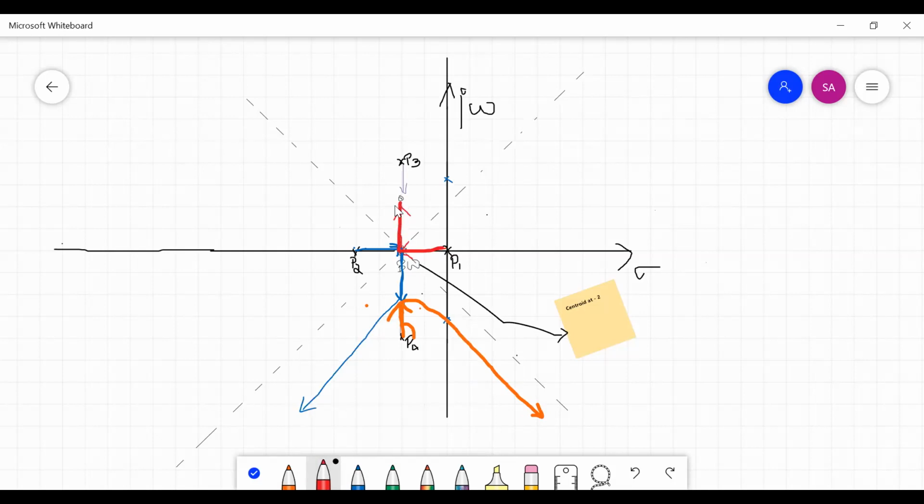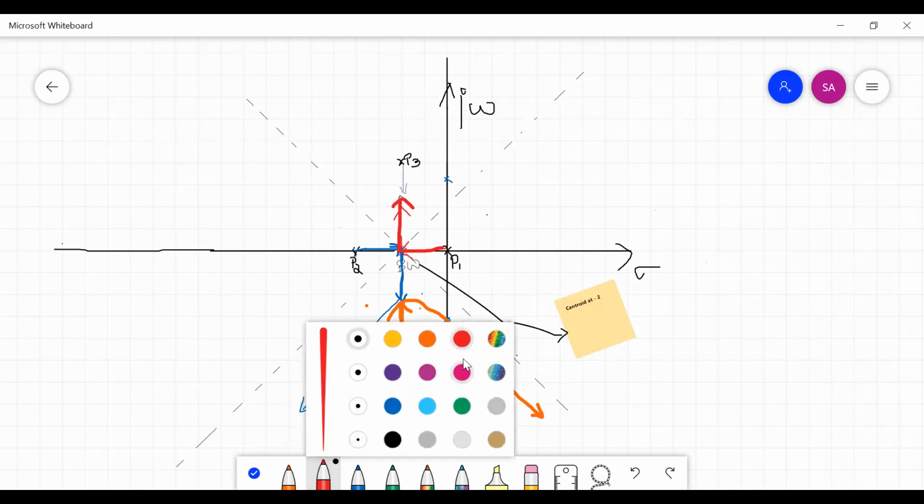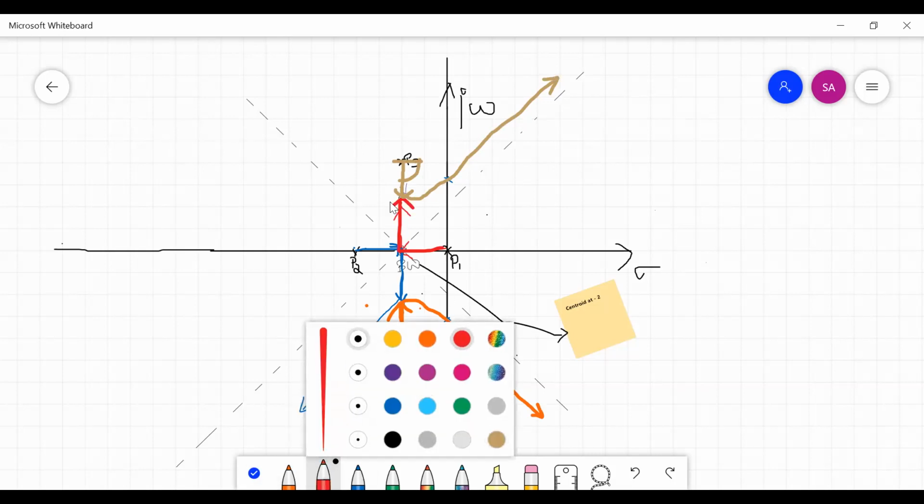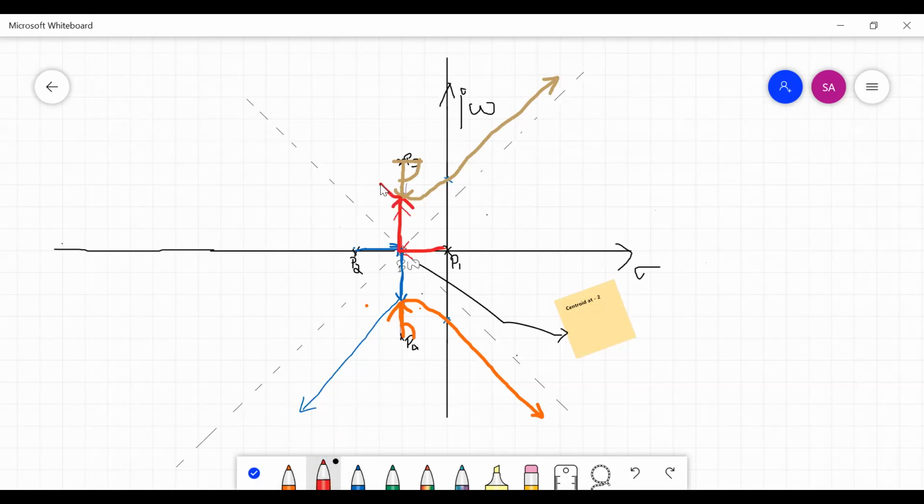Again, it saw a breakaway point. From the other end, it sees one more line coming. It sees one more root locus coming from here. Both of them meet. This is also coming out making an angle of minus 90. It comes out, meets the imaginary axis, and goes along the asymptote. Whereas this one, which came here, breaks and goes along this asymptote.